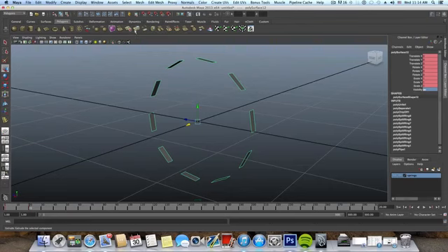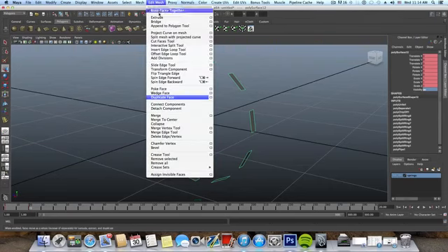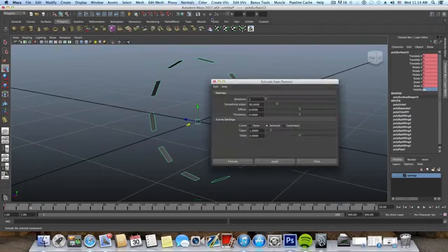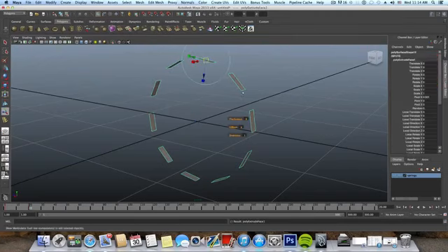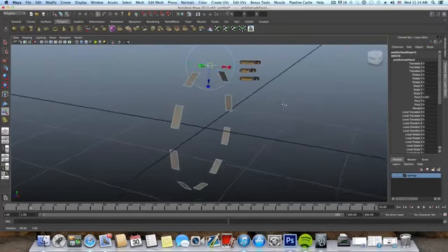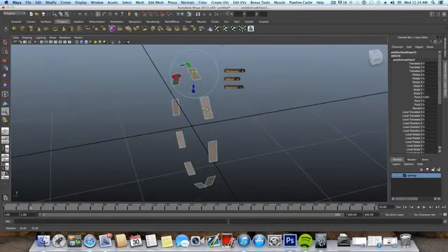We will go over this extrude box here, edit, reset settings, and then from the polygon tab we can click on this extrude. This is the same function. We click once on it and you will see that all the faces become brown with some bluish outline, and we have this gadget here.